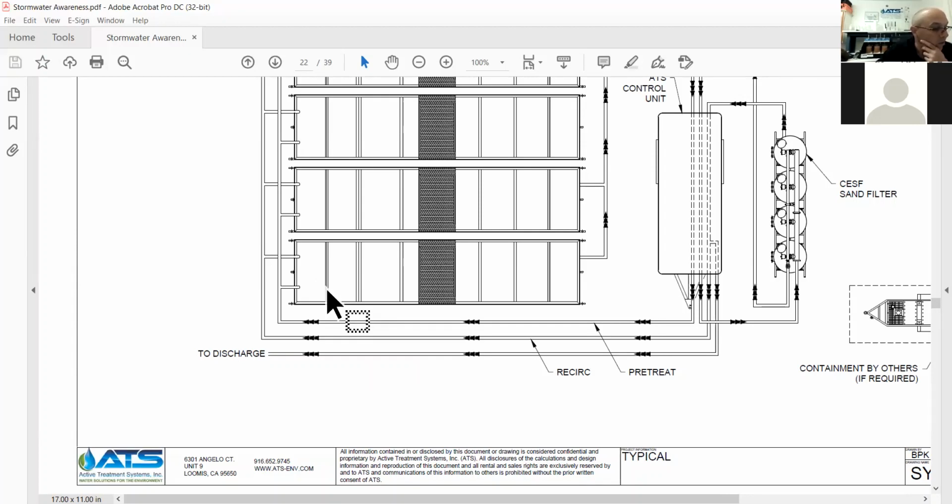Then the system size is calculated to pump and store the volume equal to the 10-year, 24-hour rain event in 72 hours. This yields the minimum system size that California water boards will approve. However, backwash and equipment or system upsets must also be considered. Therefore, a recommended system size calculation would be a 35-hour pump down.